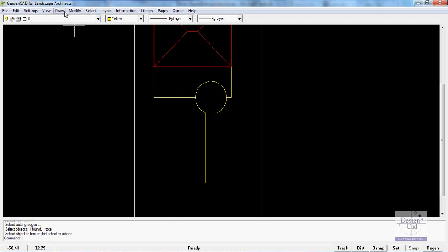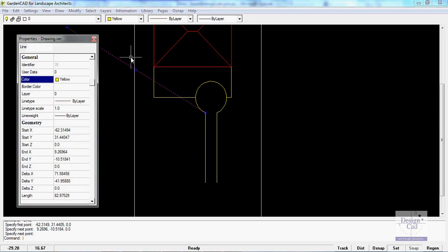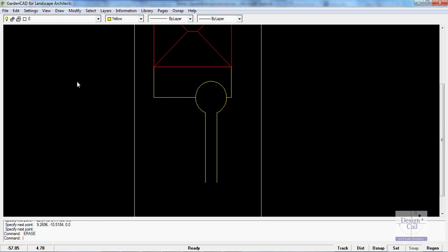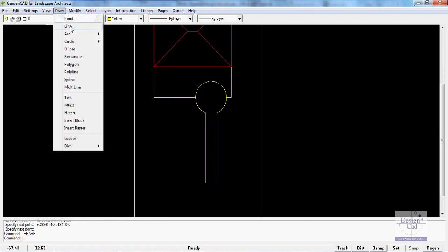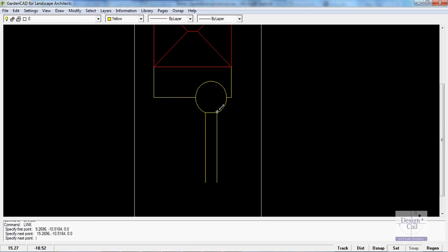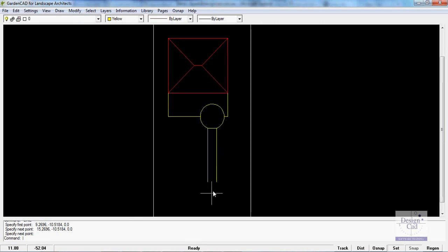So we're actually going to need a line, aren't we, from that point there. So we want to end snap there. Whoops, I've done it again. I've started a line, inadvertently clicked over there. So let's close the properties box and try that again. Draw a line from that end point to that end point, and we step from our hardwood raised deck down to a lower version of the deck onto some sort of paved path.